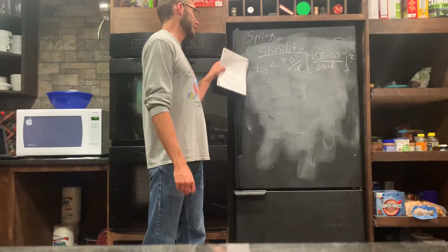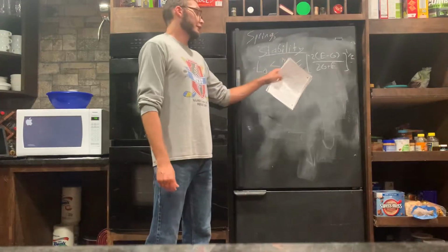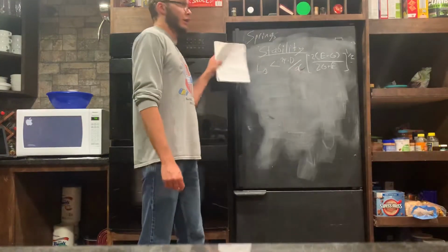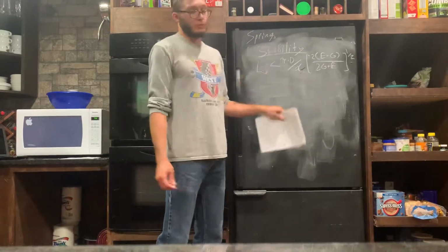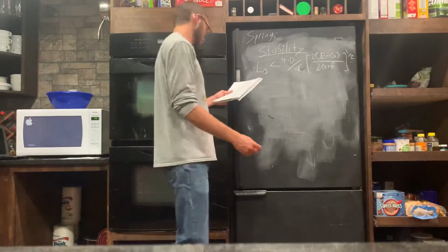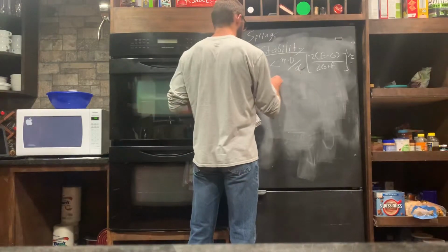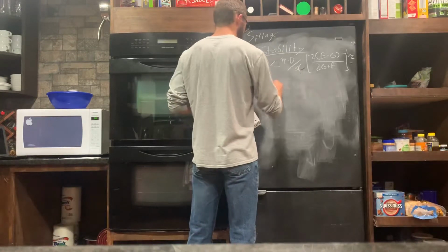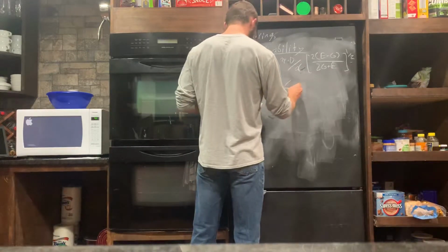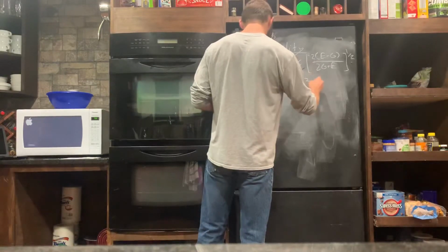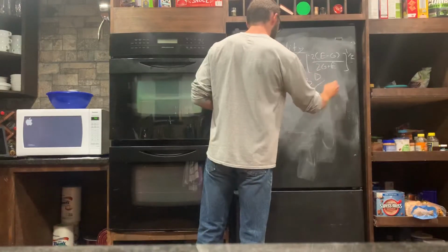And if the length is greater than this value, the maximum length of the spring, then we have to somehow shrink the spring. A common value for this would be, for example, in steel, L naught less than 2.63 times the coil diameter over alpha.